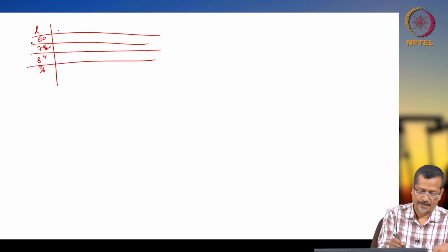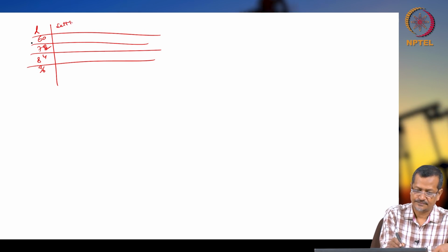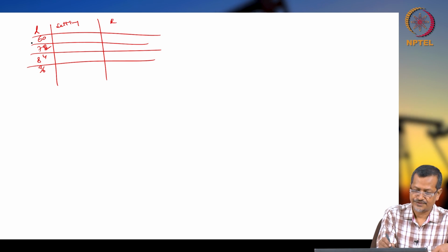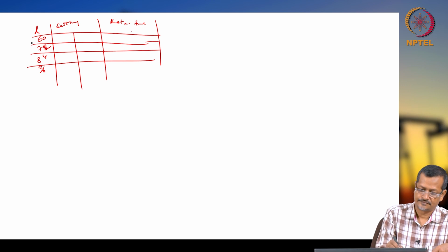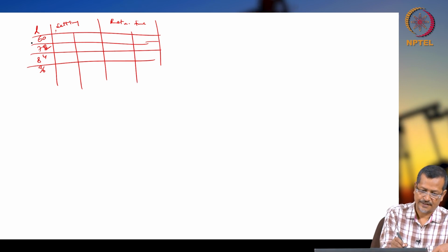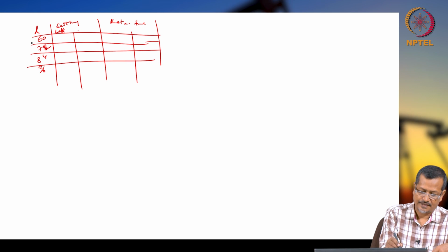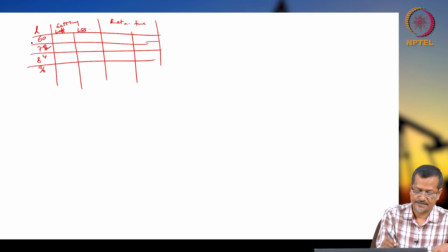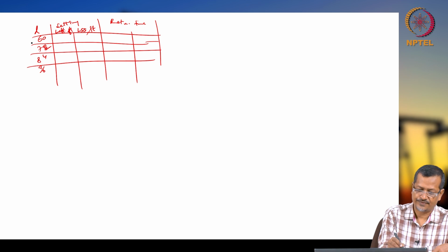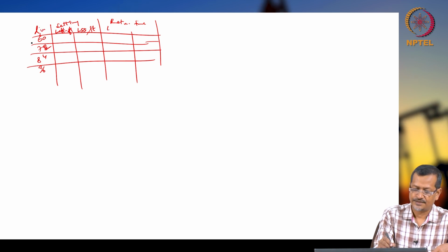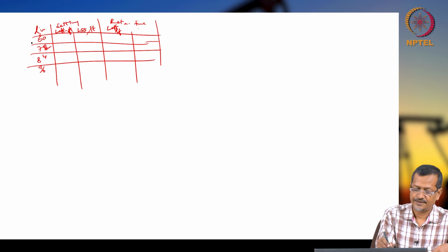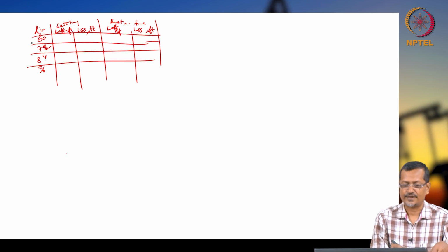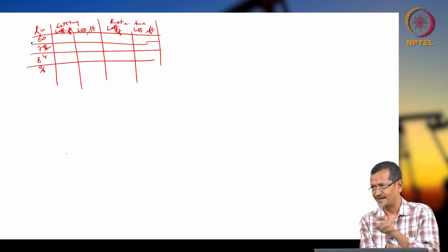And for the settling calculation and for retention time, you calculate the effective length and the seam to seam length. This is in feet, this is in inch, this is L effective in feet, LSS in feet. LSS means seam to seam length.